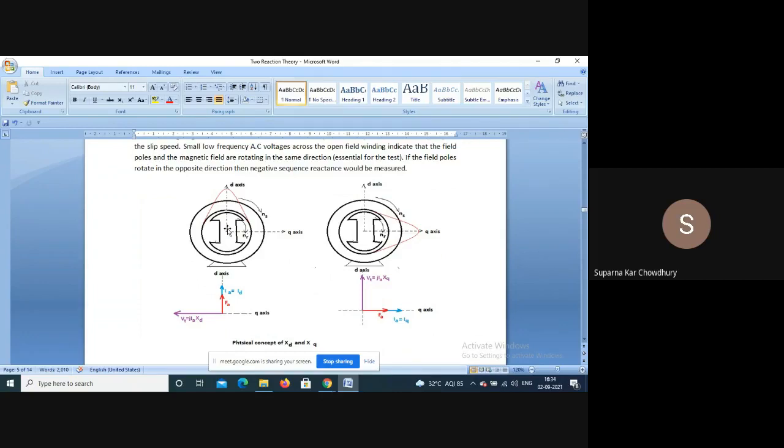The drop in leads and connecting wires is comparable when the supply voltage is small. Under this condition, when the current is small, drops in the leads and the connections are also small. So constant voltage minus small drop, the voltage will be maximum. So for this condition, voltage will be maximum, current will be minimum.